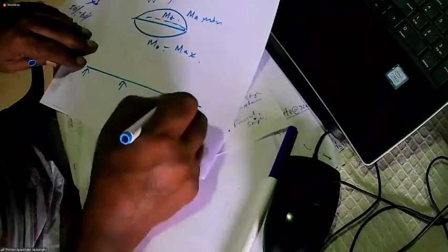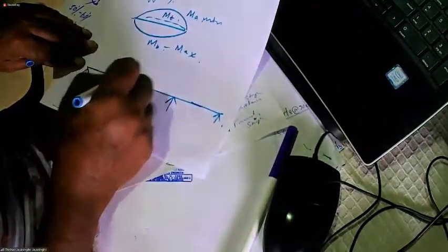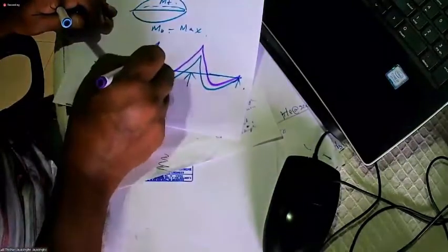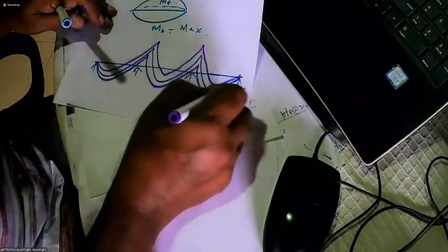So what can you say about the bending moment envelope for a continuous structure? Let's say live load is considered as a diagram, although it's an envelope. When you superimpose, the minimum moment will give something like this, and the maximum moment will give something like this.